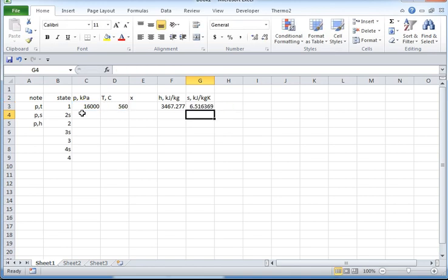There we go. Now we want to do isentropic expansion. So we go down to 4,000 kilopascal, true? And if I just want to bring that value down, don't retype it by hand, but say equal to, then grab that value. So the value in G4 will be the value in G3. Hit return. See how it brought it down? So that if I change this value over here, it will change the S for that line for state 1, and it will update that S below it. True? Watch.